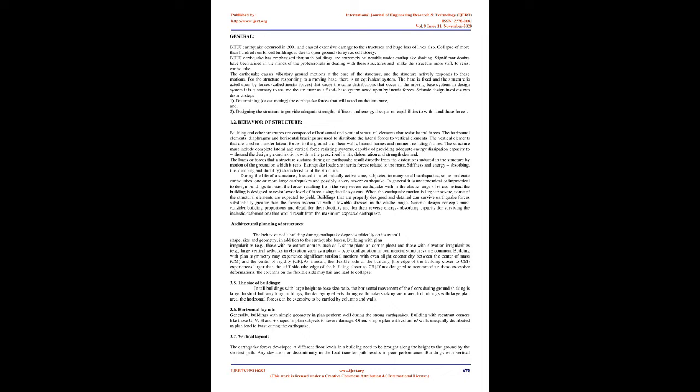7. Structural response factors, Sa/g. It is a factor denoting the acceleration response spectrum of the structure subjected to earthquake ground vibrations, and depends on natural period of vibration and damping of the structure. Average response acceleration coefficient, Sa/g. The values of Sa/g can be found either from the above graph or by some empirical equations given below, where T is the fundamental natural period.